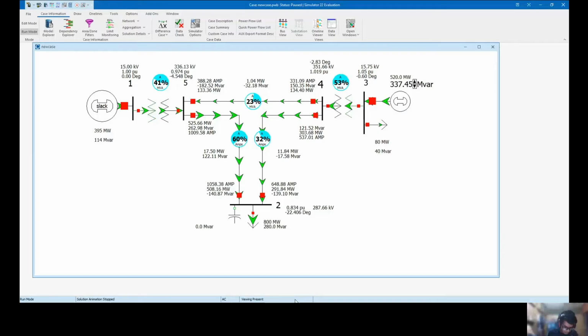Okay, so what is the suggestion to improve this project's power flow? Any ideas? Alright, as I studied the Newton method, I suggest the best way is using a UPFC, which means unified power flow controller. It has a series inverter used for active and reactive line power flow, and a shunt inverter used for voltage regulation.